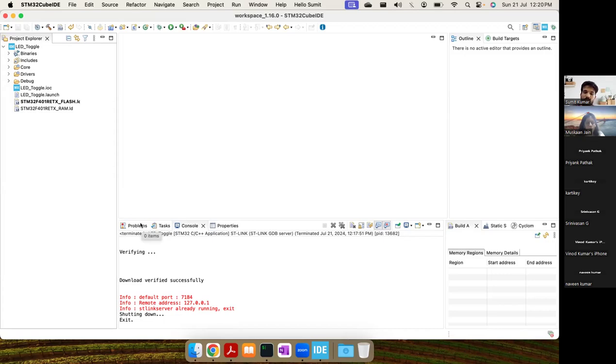Okay. As we're talking about LED, right, there is open drain, and then there is push-pull mode. Can you highlight what exactly the PMOS and NMOS circuit would be, on and off? And secondly, when you're connecting an LED or a switch, what is the need of connecting a pull-up or pull-down resistor in the configuration? As you rightly showed in our file, there is pull up, pull down, and output mode, things like this. Can you throw some light on that also?